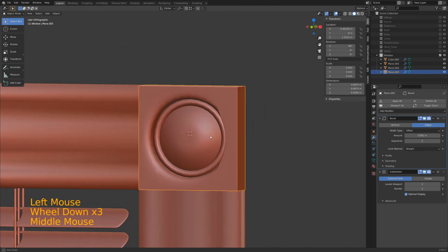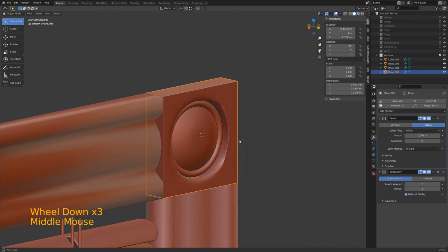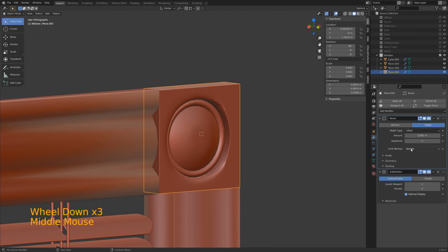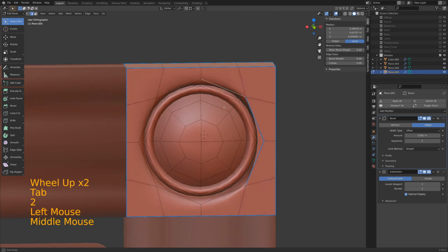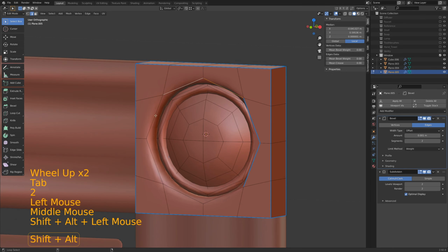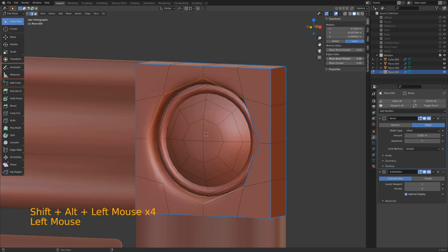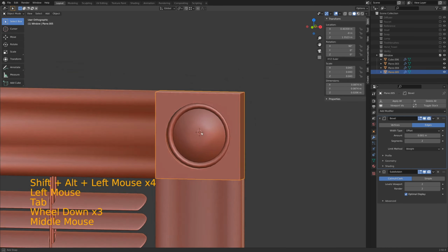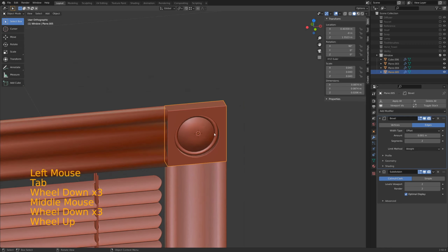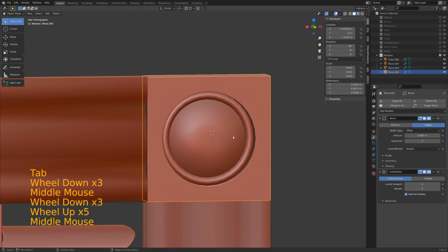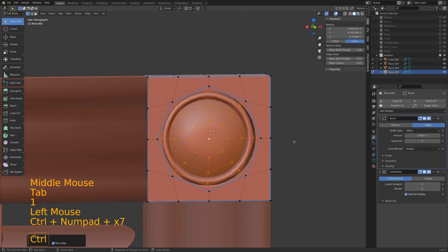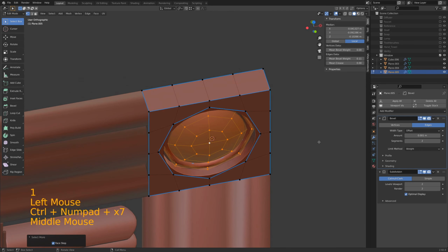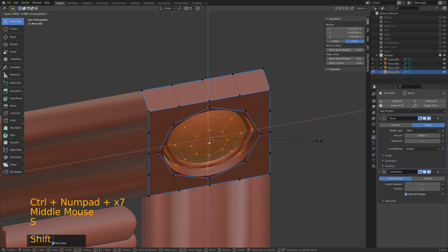Alright, I did a little bit of troubleshooting here. The problem was that the limit method was angle. It was not using our weight that we had set. So now when we go around here, as we set the weight, that is where it will be beveled. So that looks pretty good. What I would want to do is scale this on every direction but the Y.